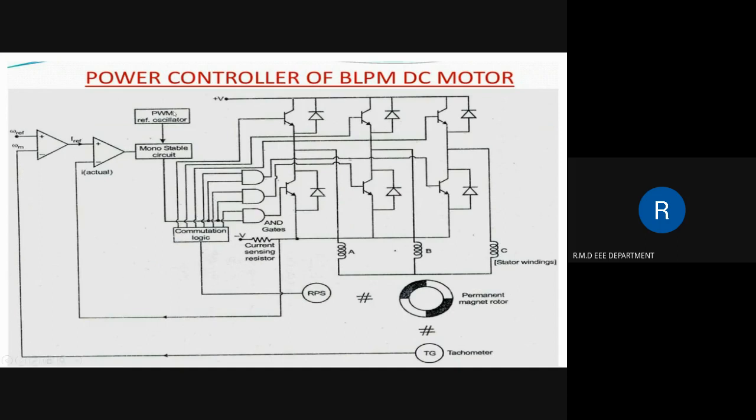The PWM signal is applied only to the lower leg transistors. Thus, these signals not only reduce the current ripples, but also avoid the need for wide bandwidth in the level shifting circuit that feeds the upper leg transistors. The upper leg transistors need not be switched at the same rate as the lower leg transistors, and they are switched at the commutation frequency.